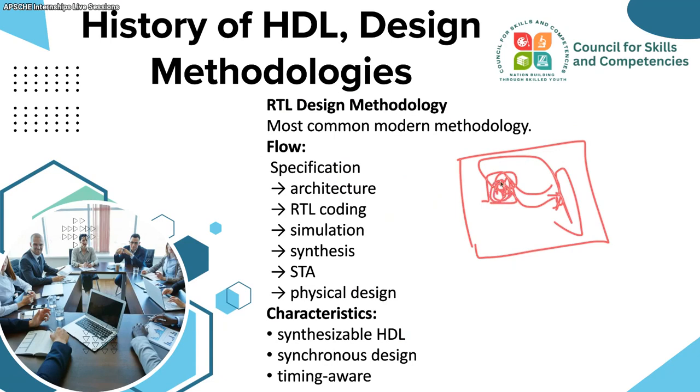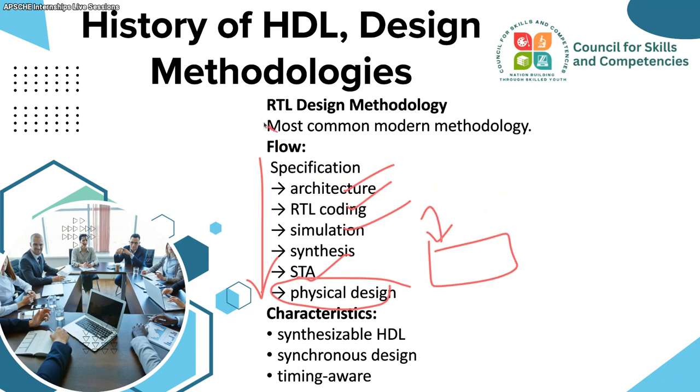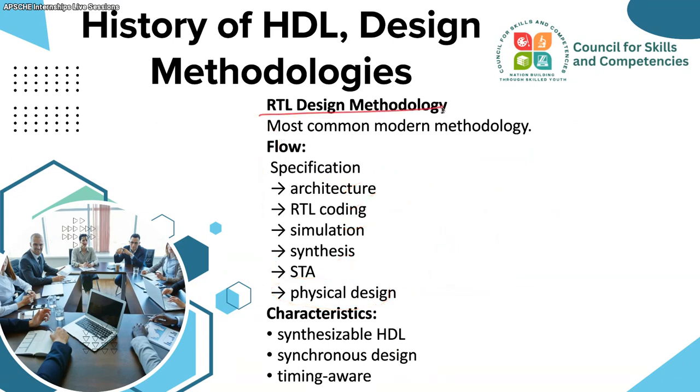So in an architecture level they will specify, and they will do RTL coding and simulation, then convert that into synthesis and static timing analysis, then go for the physical design. This is the flow for the RTL design methodology. Okay, so we will have a synthesizable hardware description language, synchronous design and timing awareness. So everything is taken care of by this RTL design methodology.